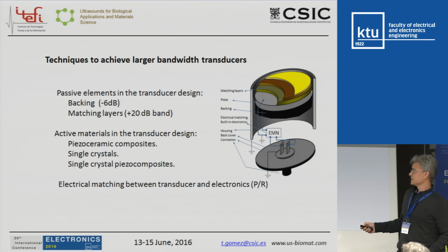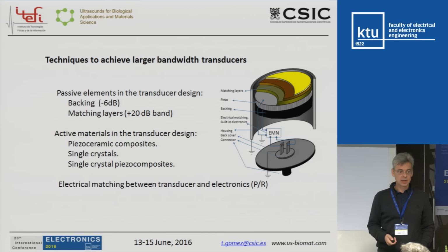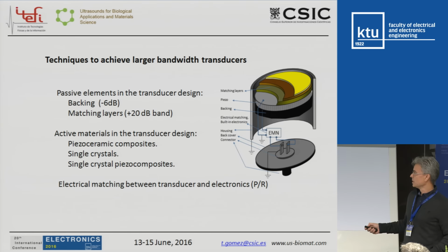Active materials. We can use piezoelectric materials that present a larger bandwidth. And what are these materials? Piezo ceramic composites, the first solution, single crystals, and now we can use single crystal piezo composites, and we are getting bandwidths with these kinds of materials above 100%, 6 dB bandwidth.